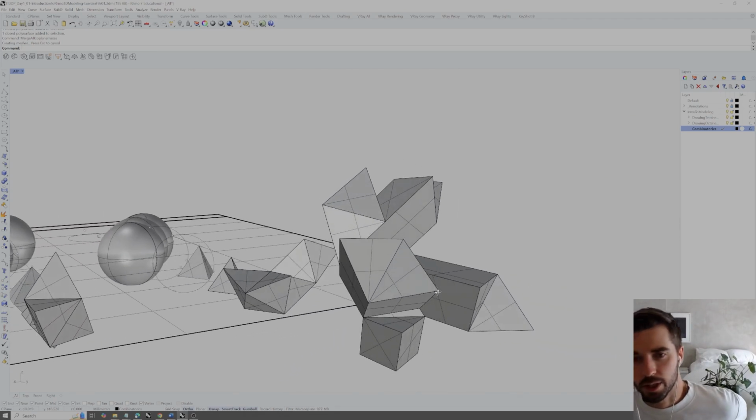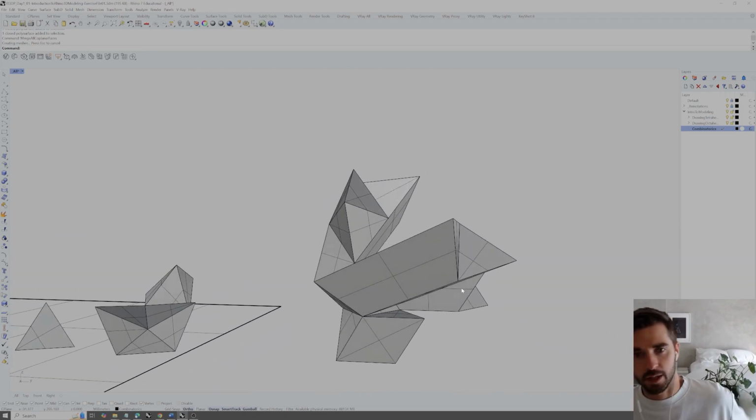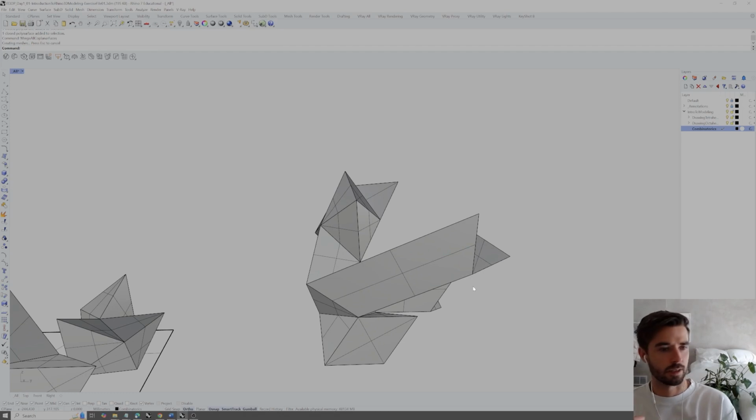So that's something that we're going to want to go in and adjust as we continue editing this geometry. One other thing to consider is when you're performing that Boolean operation, if you get a failed operation, just go ahead and Boolean individual elements in steps. So you kind of sequence through it, adding one to another. Just take it one by one, that's totally fine. Sometimes it has a difficult time where edges are perfectly aligned on one edge.